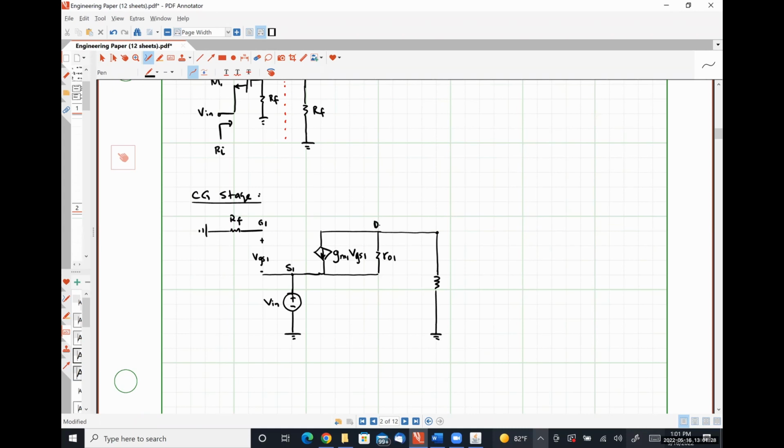In our drain terminal and ground, we see resistor RD. And that drain node is also where we take our output voltage, Vx. So does this look reasonably like what the left-hand stage should appear as, with channel length modulation included?